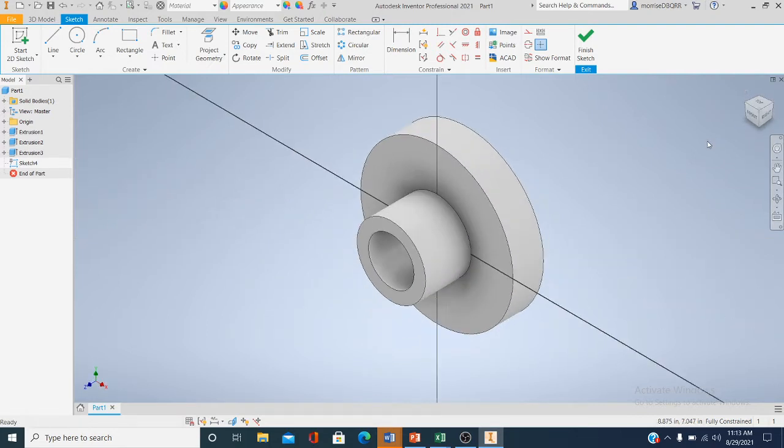All right. Now I'm going to get my isometric view. Now, how many holes do we want? I'm going to select 6 holes. So what I'm going to do, sorry, my allergies are acting up today. I'm going to select circle center point, and I'm coming right here on this line. Okay, you see now it's not turning green, but it knows it's there on that line. Right here on the y-axis, I'm going to click, and I'm going to drag out a circle, and let's make it 0.75. That sounds like a good number.